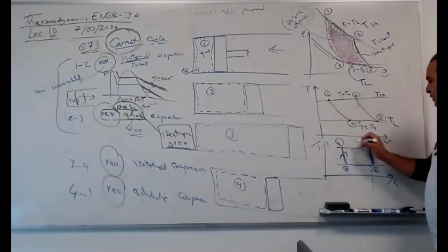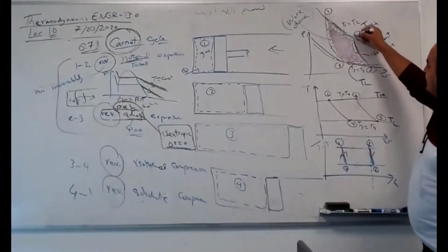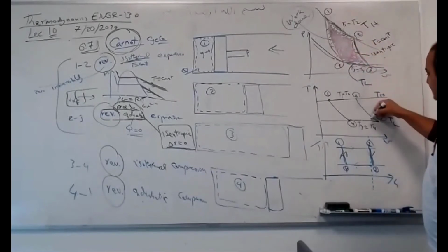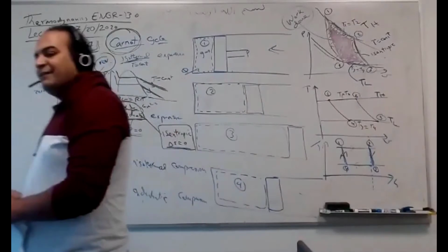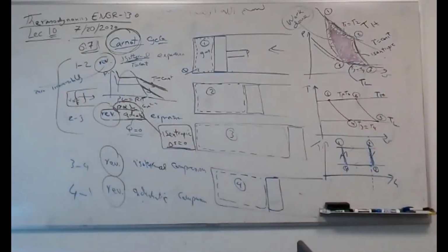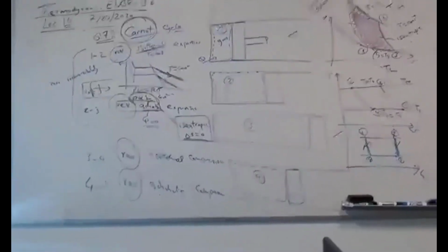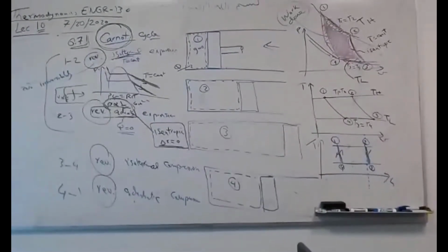It means S equal constant. So this looks like the S equal constant adiabatic process, S equal constant in the PV diagram, S equal constant in the TV diagram, while they are vertical lines in the TS diagram. That's why sometimes the TS diagram is one of the best diagrams ever, because it's just a rectangle.